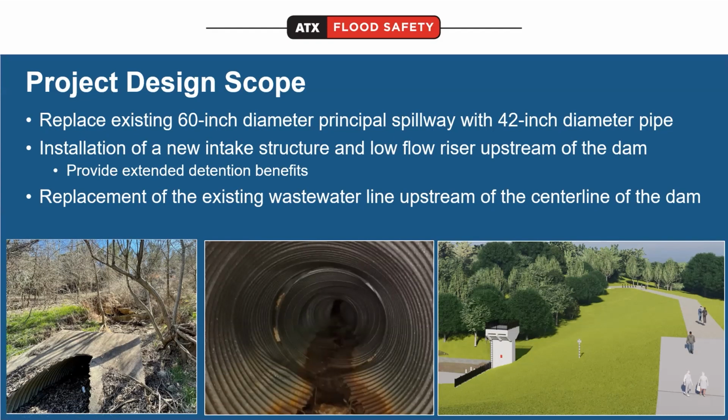So that's going to allow us to retain the water in the pond a little bit longer, just over a couple of days. The pond is still going to be considered a dry detention pond. Most of the time, it's still going to be dry. But during significant rain events, we're just going to be able to hold the water for a bit longer, which provides some water quality benefits because that allows some of the sediments to settle down and cleaner water to go downstream. So I know there's St. Edward's Park downstream, for example. This would provide some water quality benefits, meaning that the water downstream would have less sediment in it.